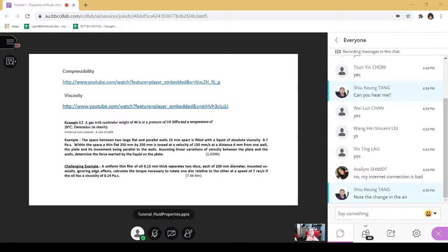Inside the bottle, because there's no relative movement, the pressure in the air is basically the same as that inside the liquid. So when we release the lid of the bottle, the pressurized air comes out first, and at that time the pressure of the water is also higher than atmospheric pressure, so the water comes out, because of the pressure difference.